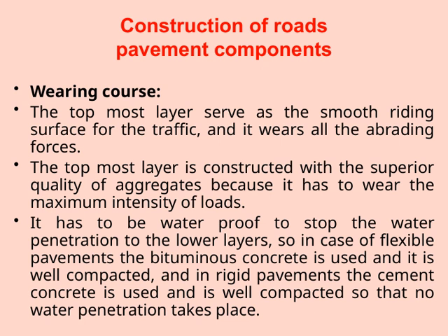We need to prevent water from penetrating into the lower layers of the pavement, as water can weaken the entire structure. In flexible pavements, we use bituminous concrete, which is well compacted to create a tight, waterproof surface. For rigid pavements, cement concrete serves the same purpose, and it is also carefully compacted to ensure no water can seep through. So, in essence, the wearing course is designed not only for durability and smoothness, but also to protect the underlying layers from water damage, which is vital for the longevity of the entire road.